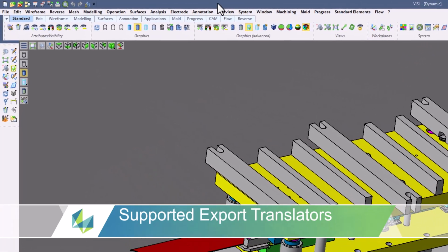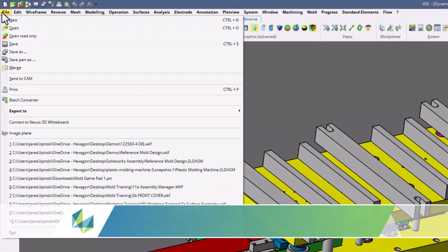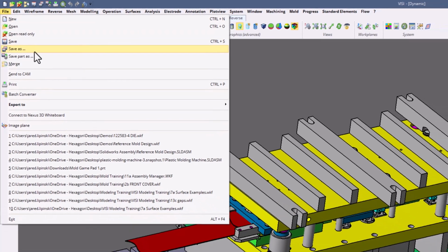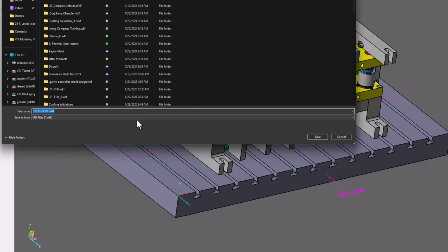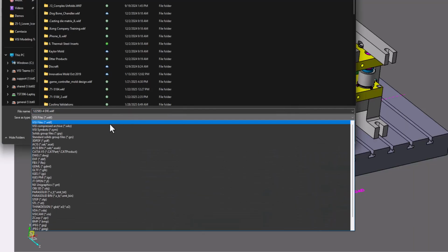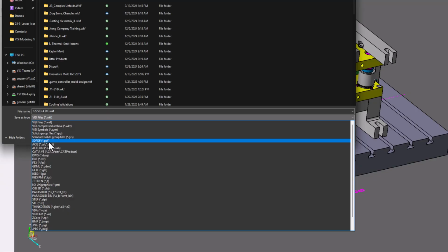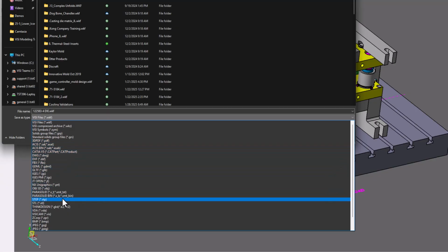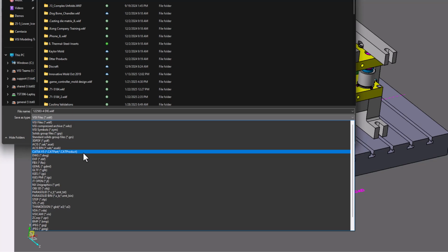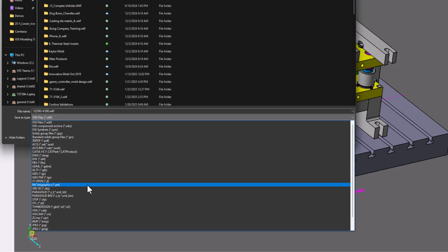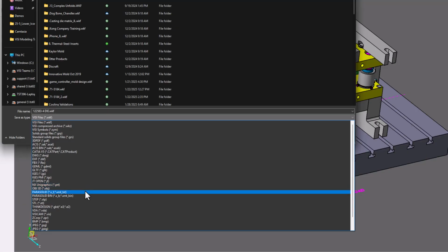Once the assembly tree is created from the assembly view, we will now review exporting the tree out for other programs to import. In our example, we're going to export as a 3D PDF, as well as a step file. Please note that the way we are exporting is the same in other translators. Visi also offers a wide range of export translations as well, such as Catia, NX, Parasolid, and other general translators as well.